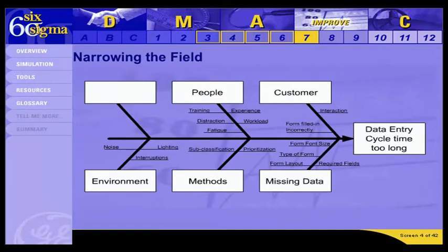The fishbone exercise is the first part of a brainstorming session. It serves as the container for all suggested factors. The second part of brainstorming involves tapping historical data, process knowledge, and process documents to eliminate as many factors as possible. Any factors not conclusively eliminated will be tested with a technique called design of experiments to validate their significance.